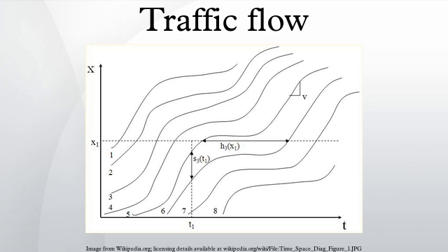Traffic assignment. The aim of traffic flow analysis is to create and implement a model which would enable vehicles to reach their destination in the shortest possible time using the maximum roadway capacity. This is a four-step process. Generation. The program estimates how many trips would be generated. For this, the program needs the statistical data of residence areas by population, location of workplaces, etc. Distribution.